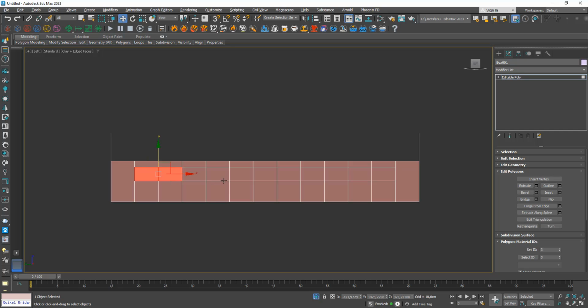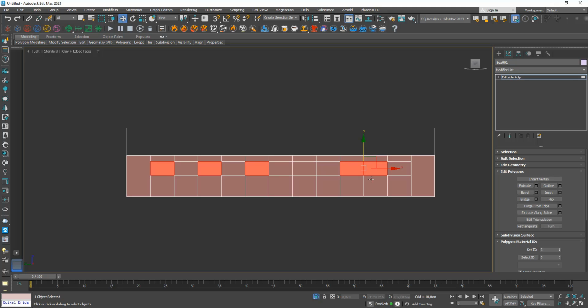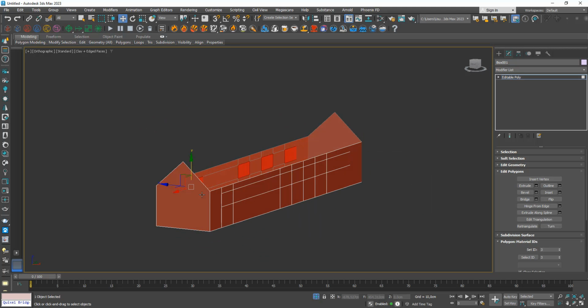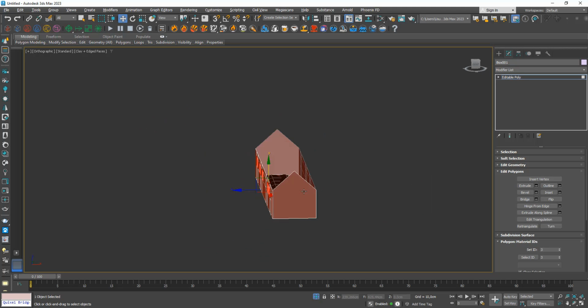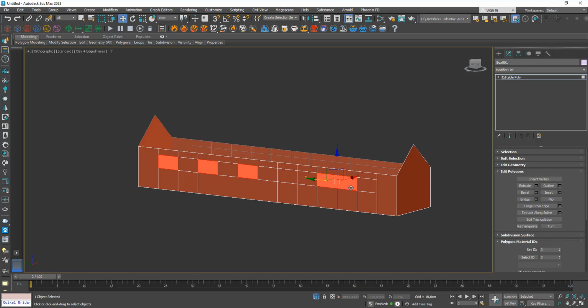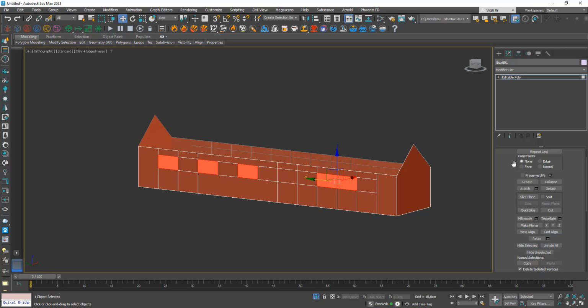Let's just go ahead and pick something like this, and let's avoid actually the symmetry. So to unselect objects in 3ds Max, you only have to press the Alt key. Let's create something a bit more random, like so. We are only going to be selecting the polygons from this side, as this side over here, we're not going to be actually seeing it on our render. So while selecting these polygons, we're going to go inside Edit Geometry and detach them so that we can work on them separately.